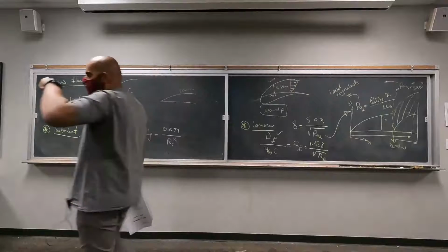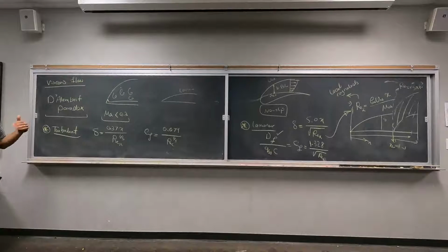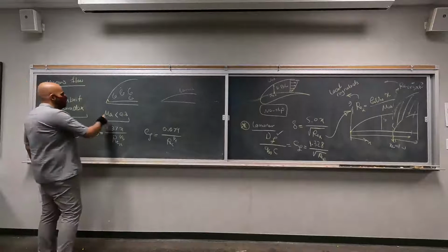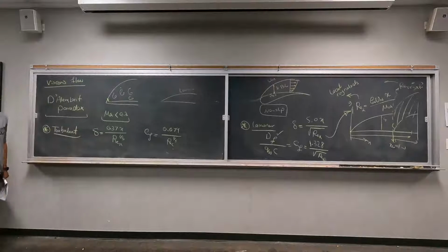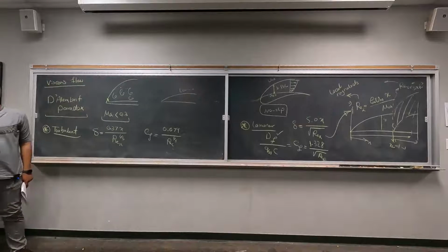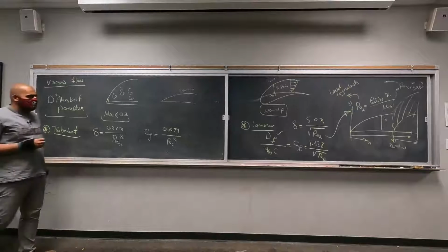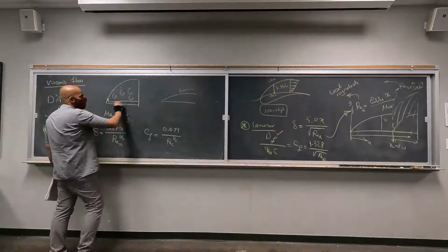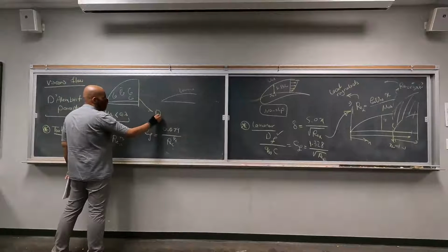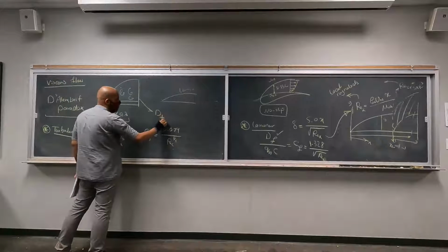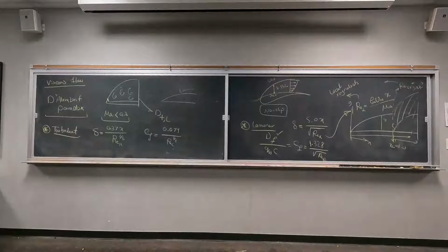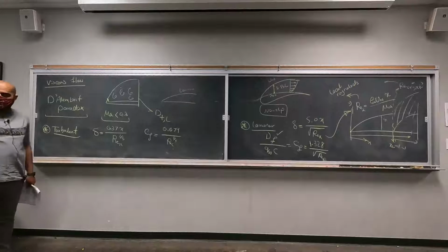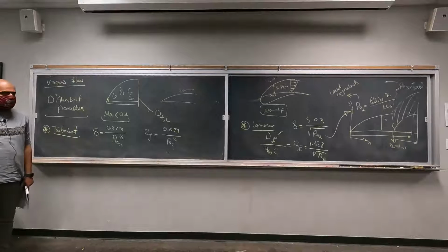What if we calculated the turbulent flow, because the transition only happens in the turbulent? What if we calculated the drag force, assuming that the turbulent flow starts from the beginning, right? And we calculated the drag force for that part. You can definitely do that, right? So calculate the drag force. Let's call it D turbulent and L for the whole plate. This is what you were saying. That was the starting point, right?